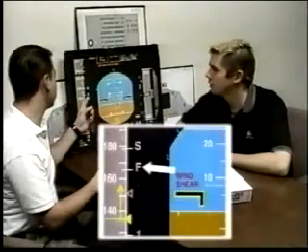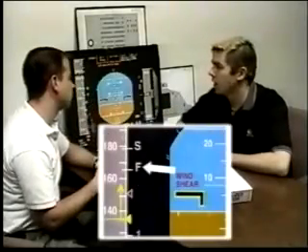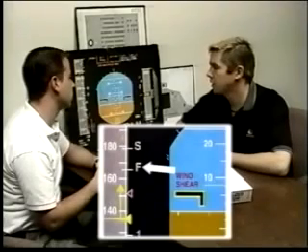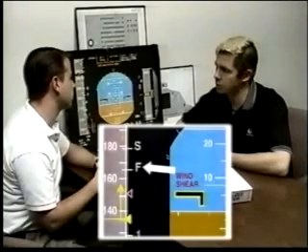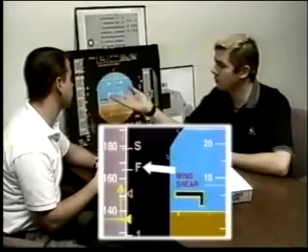Now we have an F speed. So describe F speed for me. F speed is basically the same thing as S speed, except F speed is related to flaps 2 or flaps 3. It's called minimum flap retract speed because we have flaps out when we're in position 2 or 3. And during takeoff, as I accelerate through F speed, I can then raise the flaps from either 2 or 3 up to 1. And again, if I'm flying around in the approach phase and I have autoflight completely hooked up, I'll be flying at F speed.